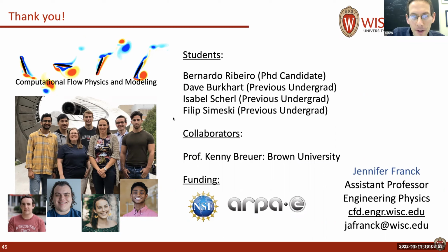So I've seen more work about generating propulsive forces from flapping foils, not so much about extracting energy with flapping foils. So it's really interesting to see what the fluid mechanisms are here. So I guess a lot of the power you're getting is from lift forces, right? Yeah. So when you have just a single foil, if you increase the angle of attack, the lift keeps going up until you get to the stall angle. And then the lift drops and the drag goes up.